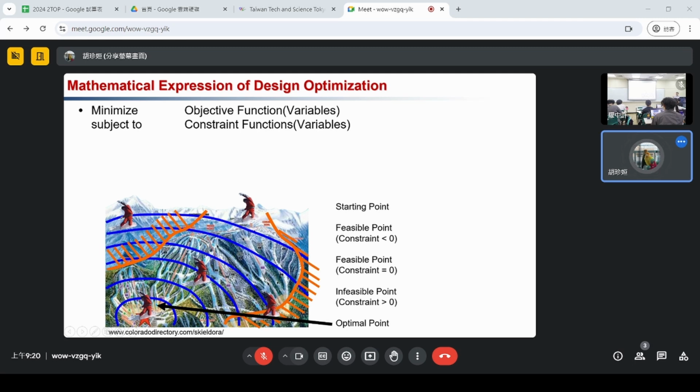And maybe you didn't choose the right design variable. The thickness may not be the best one. Probably it's actually the radius of the corner. So you need to make a decision what would be the design variable. Can you have multiple variables? Yes, you can.